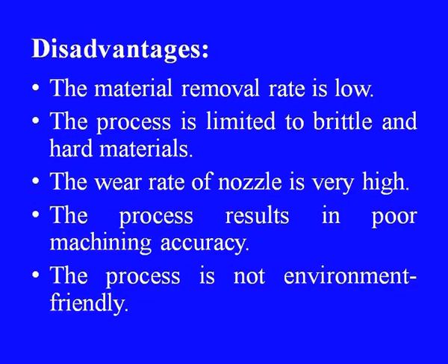Let us also look at the disadvantages of this abrasive jet machining process. The process, as we have already discussed, is basically a finishing process or low level cutting process. Therefore, the material removal rate in this process is usually very low.